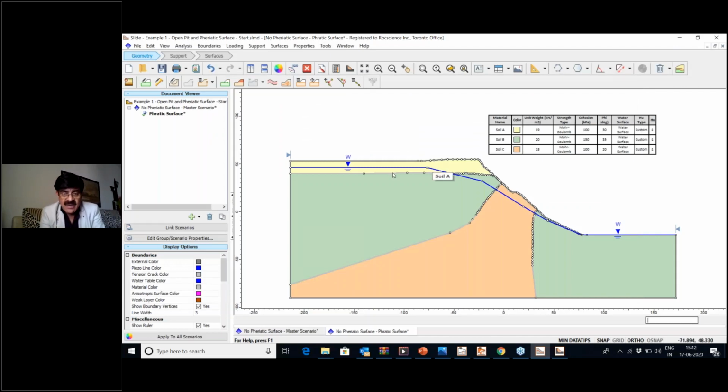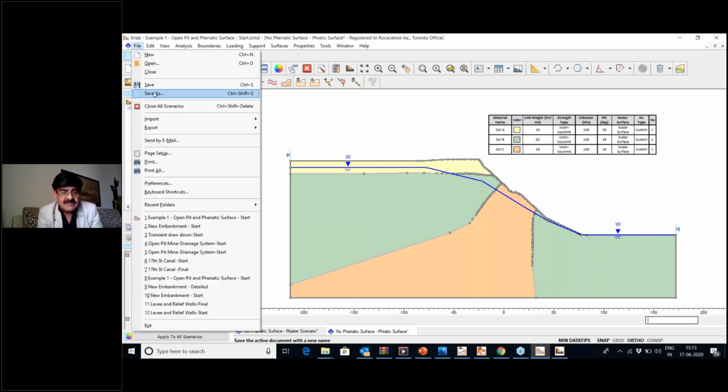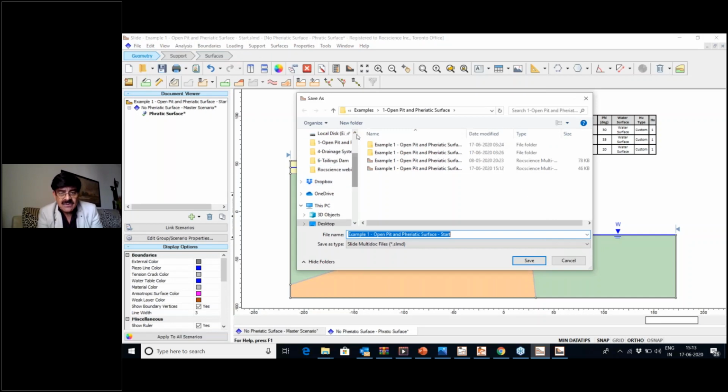So you can see the water table has been applied, and you can immediately see that the table has been updated, and you have the water surface now. And HU is 1, so as I said in the beginning, we are on the conservative side. And so let's run this analysis now. So I need to save it somewhere first so that I can then compute.